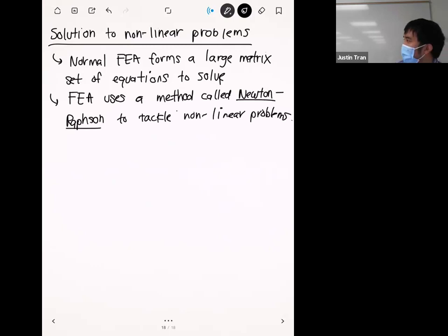And at this point, I'd say it's a pretty ubiquitous method. And so, I'm pretty confident in saying that a lot of FEA software actually uses this because it's just so effective at what it does. Okay. And so, again, we're not going to go into the details of that method, but one important detail about how it works is that it performs an additional approximation step. Okay. And what it's essentially doing is taking your nonlinear equation and intelligently turning it into a linear equation. Okay.